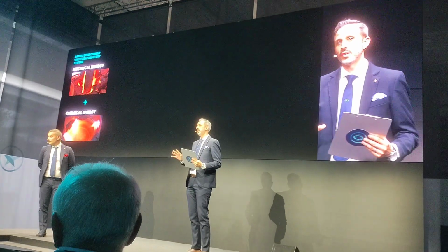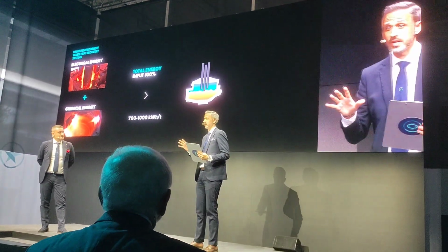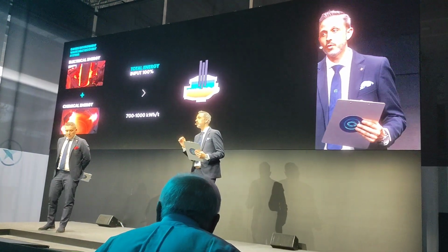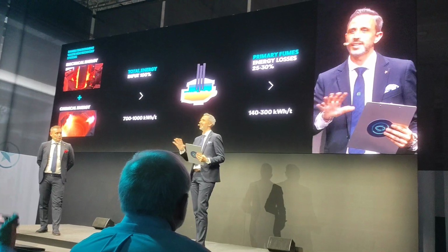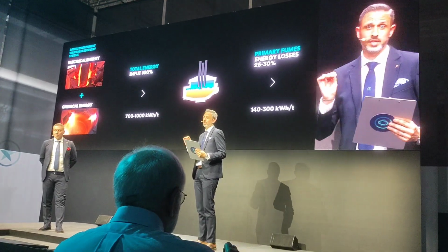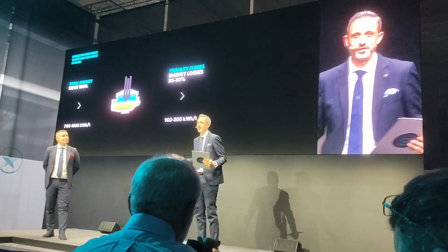If we consider that these two contributions provide the 100% energy input in the furnace, the interesting information is that 25–30% of this energy gets lost in the primary fumes. And this is a really significant number. So, let's try to recover all this energy.